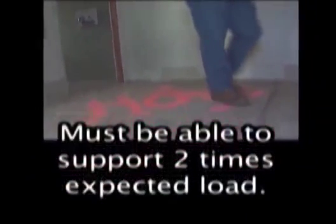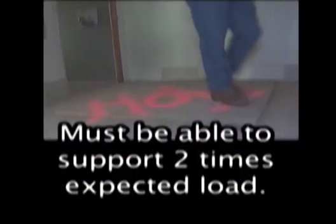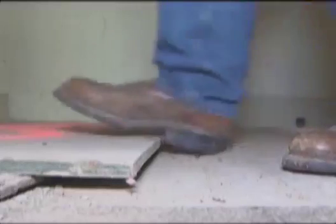Covers should be used to keep employees from falling through holes in walking/working surfaces, and be able to support at least twice the axle weight of the largest vehicle that might drive over the cover, and at least 2 times the weight of employees, equipment, and materials that may be imposed on the cover at any one time. A cover should be well secured to prevent accidental movement and be marked with the word "hole" or "cover."